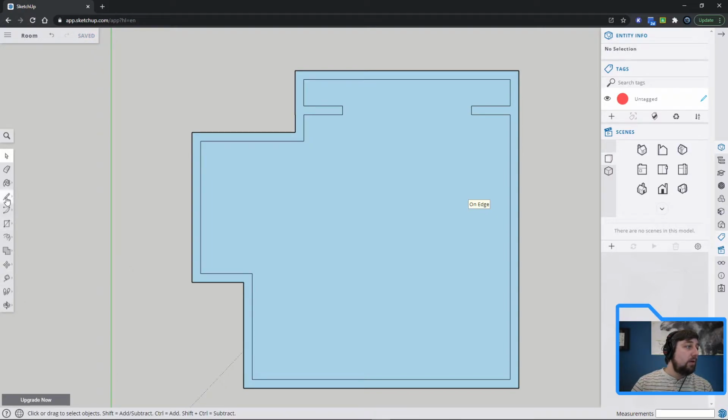Let's make our actual opening for my doorway here. So looks like from this corner down, 6 inches. Where's the end point? Go over this way. Oh, that's probably 4 inches, let's do this correctly. So 4 inches normally is your door jamb width.